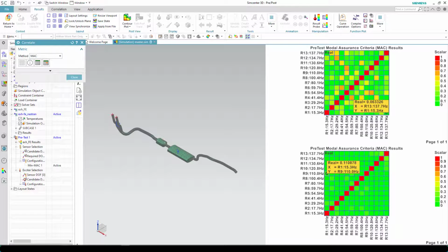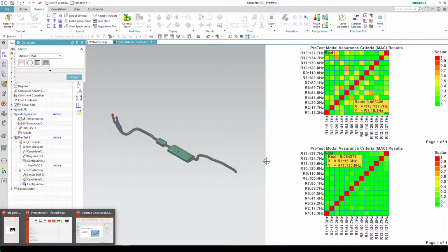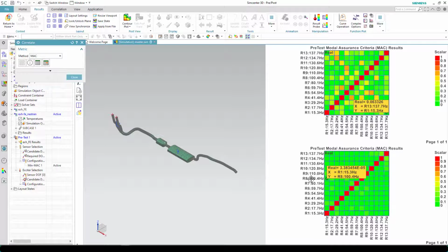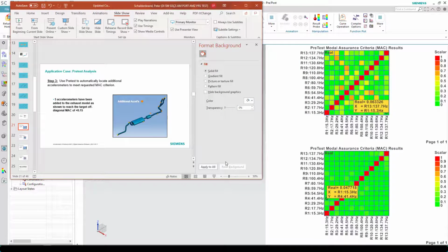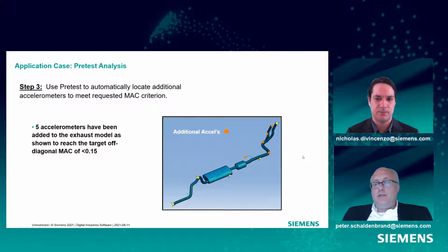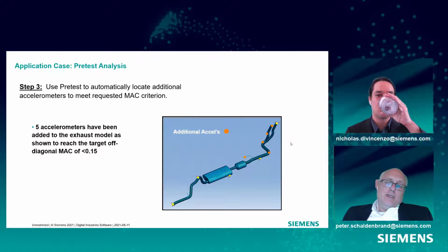So here we've used our simulation model to help the test engineer avoid, I think, what we called in the last session, spatial aliasing. Right. You know, under testing, I guess, not enough points. But we could over test too. So, I mean, if we measured at 100,000 locations, that would be very time consuming and not yield us more information than maybe those 8 locations.